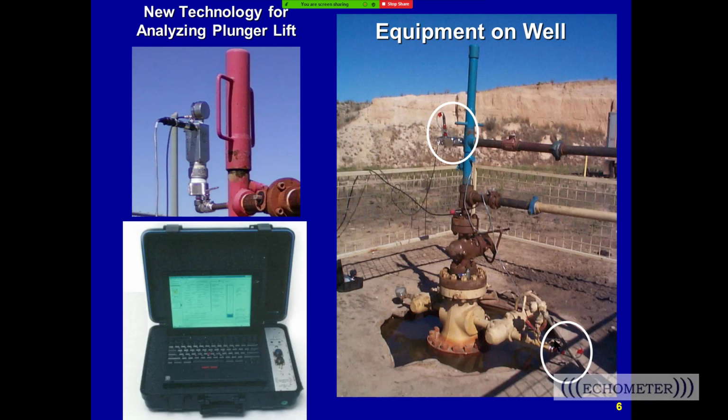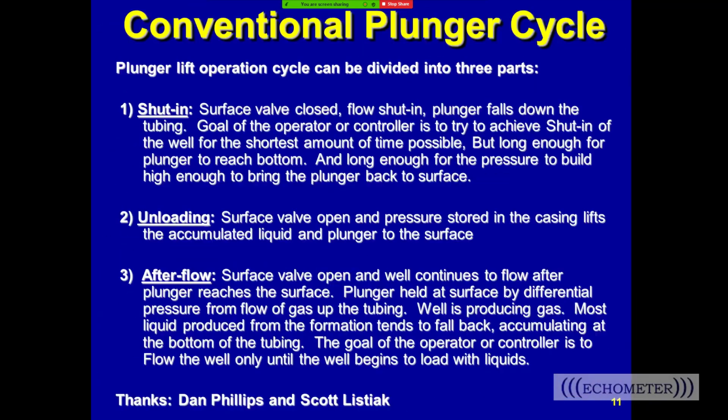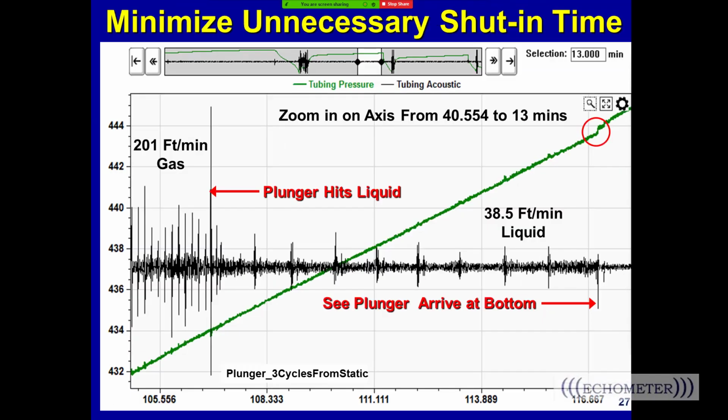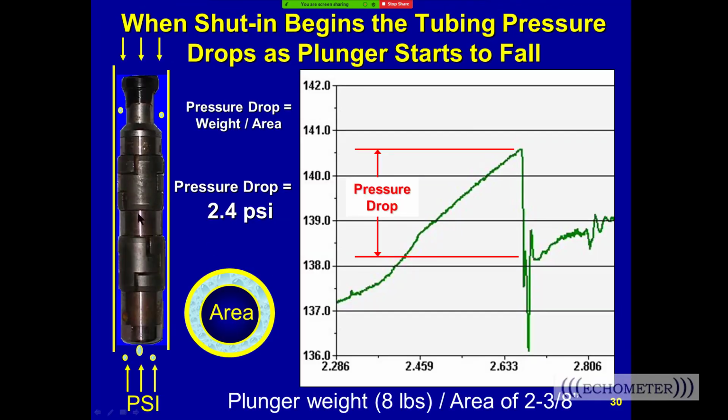Yes. We have a question from Mo Yunus. He's asking, could you explain dimensions of plunger and how much spacing between ID tubing and OD plunger? But then I think that was answered on slide number 30, where you have a comment on an 8-pound plunger on a 2 3/8 OD. Yeah. So the pads actually touch the well. So the pads are in contact with the tubing wall.